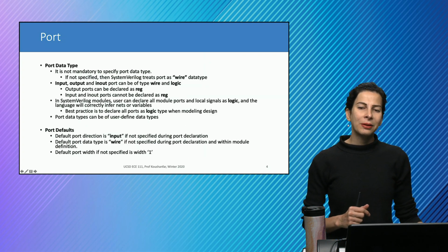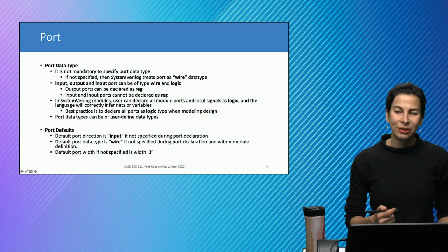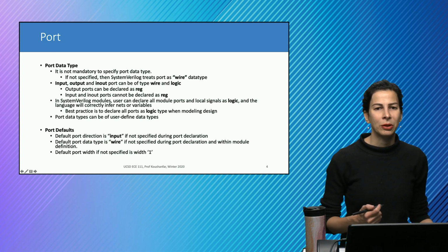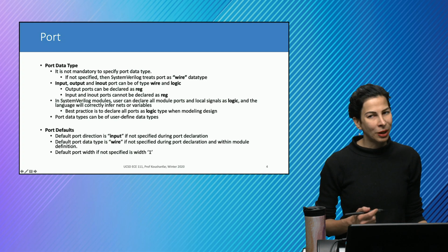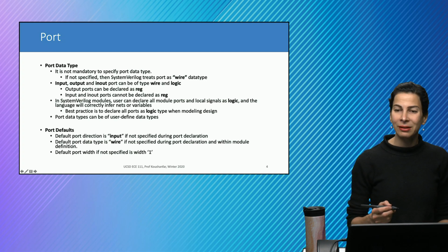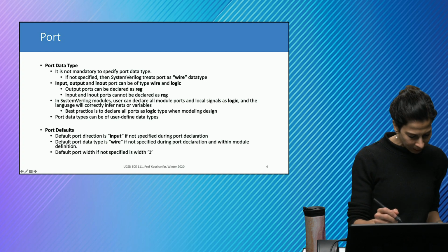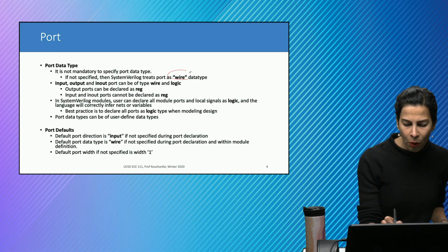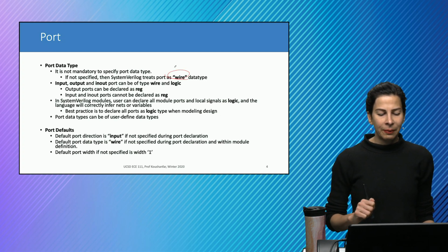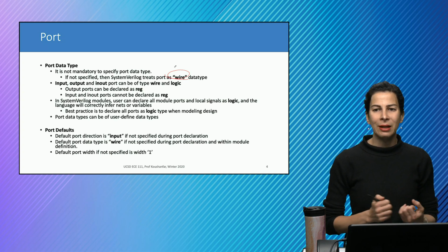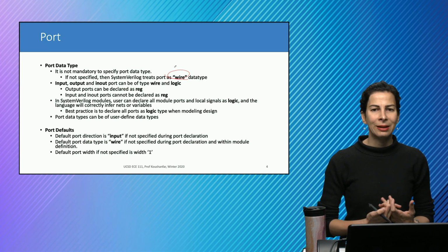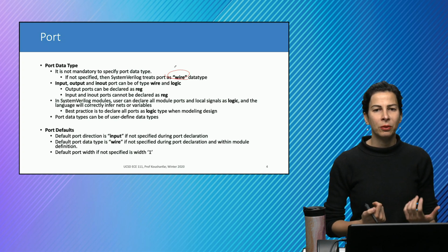It's always a good practice to determine the data type for each port, but it's not mandatory. If you do not specify the data type, it will be interpreted by SystemVerilog as a wire. But if you specify it, you could specify input, output, or in-out as wire or logic.